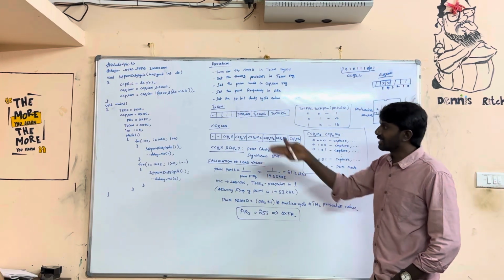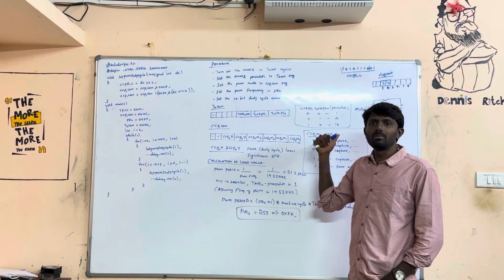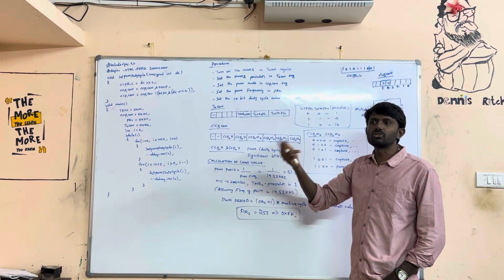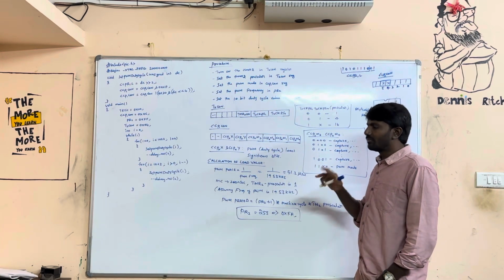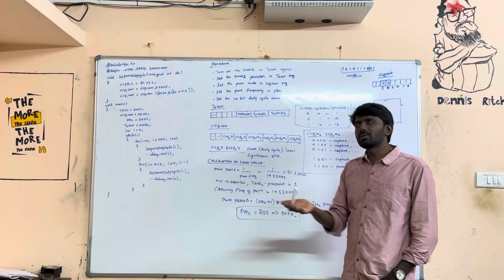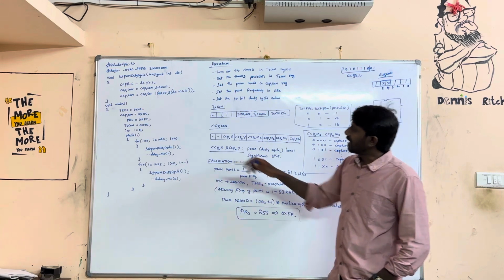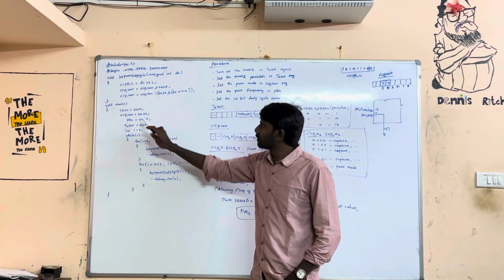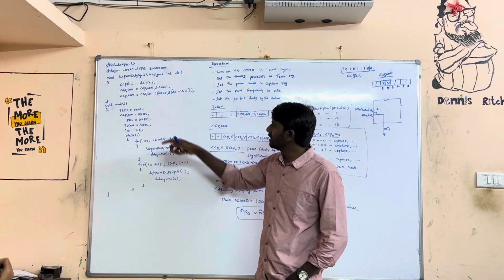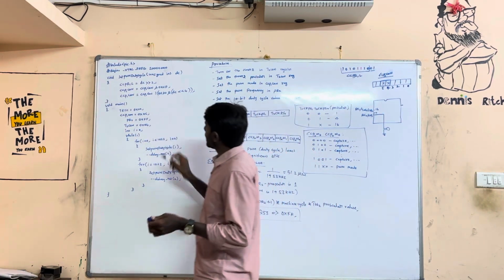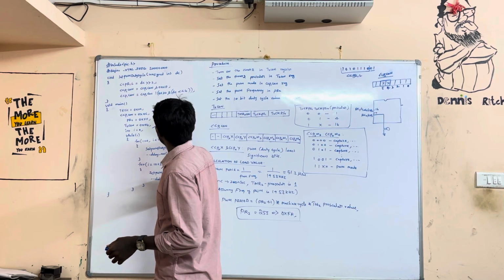After that I need to do configuration for the PWM also, otherwise it will act as just an output channel. Since I am connecting one LED, we are expecting output voltage in that C port. And after configuring it, now I am going to do the configuration for PWM. You have to do both configurations. Got it, right? So now these 3 lines are PWM configuration.